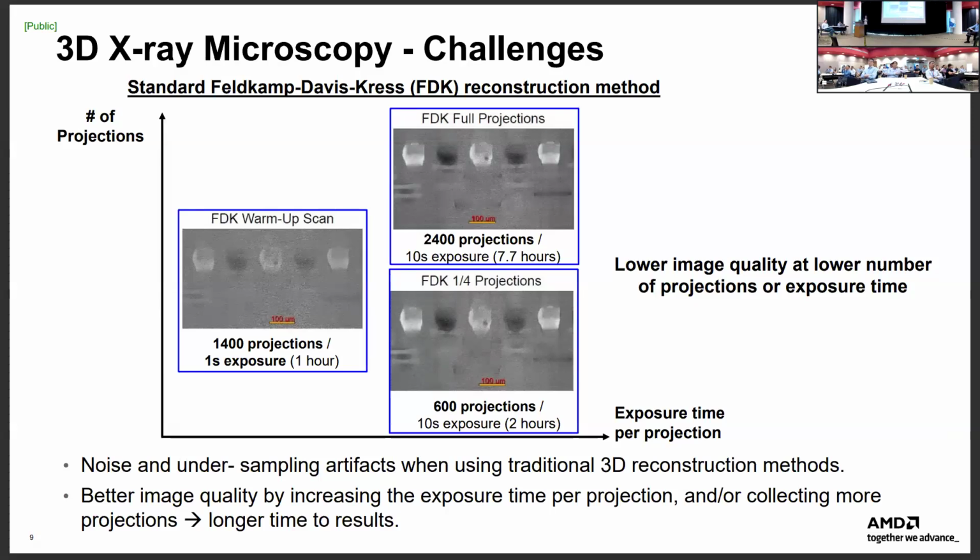So another one of the challenges we're facing now, I think Dr. Xiaoli Li, you talked about the 3D X-ray imaging. This is one of the more commonly used techniques now, because in acoustic imaging it's very hard to see 3D structures. Generally you're only seeing 2D in acoustic imaging. So 3D X-ray has become the go-to method for imaging interconnects. But as you know, for 3D X-ray, there are issues with noise. If you scan too quickly, meaning exposure time is low, the detector doesn't collect enough data, and you get very blurred images.